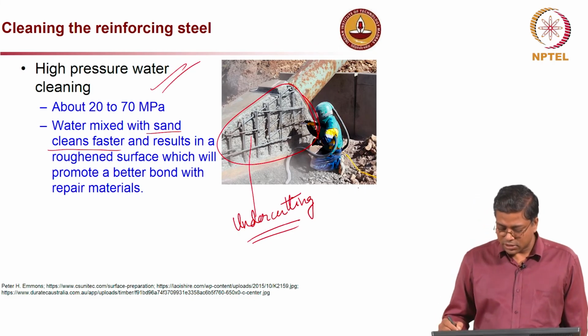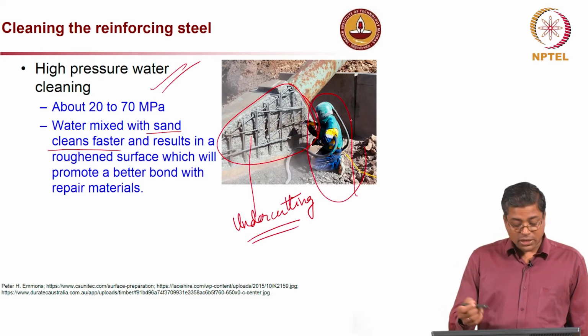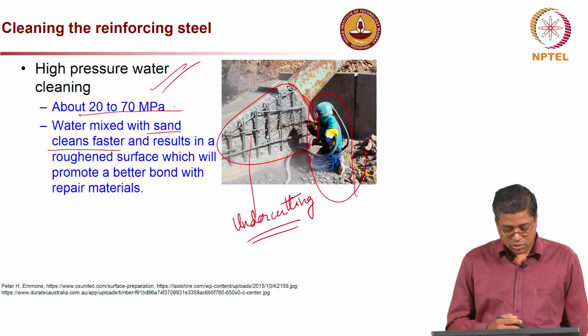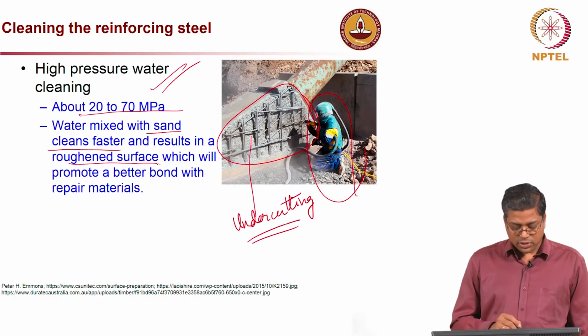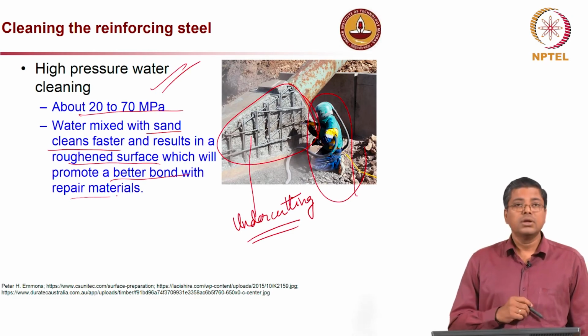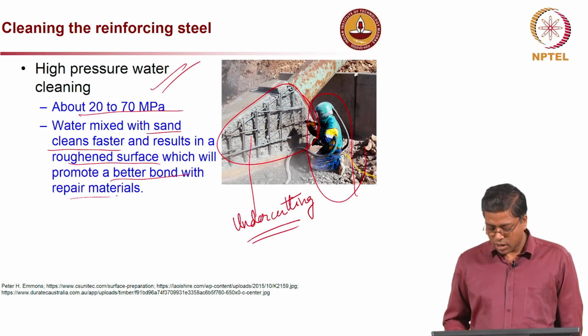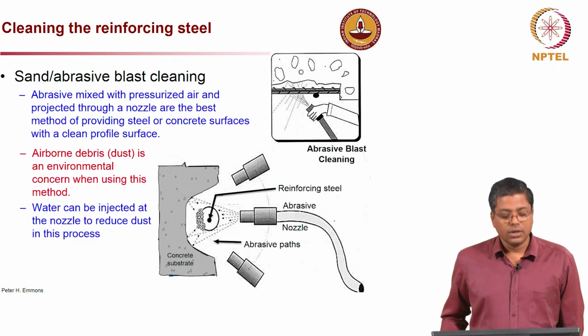You can see the person here in full gear, fully covered, because the pressure is very high. You can see here 20 to 70 MPa pressure is used, and it creates a roughened surface which will promote better bond with the repair material. So, it is very important to use these high quality, specific tools for achieving the target.